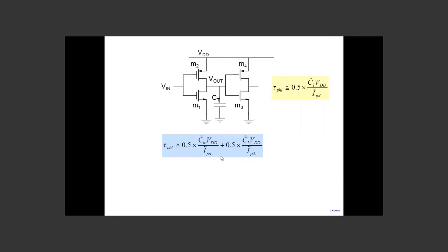All right, so the delay that you see here, I've been saying that delay comes about because of this expression that you see here. And CT is made up of two parts. CT is made up of an intrinsic part, intrinsic to the inverter, and a part which is because of the load here. So we can break the delay, as I've been saying, into two parts here, intrinsic delay and an extrinsic delay. And intrinsic delay, so this was 13 femtofarad and this was 7 femtofarad here. Now, intrinsic delay is not exactly, but roughly constant with respect to the size of M1 and M2.